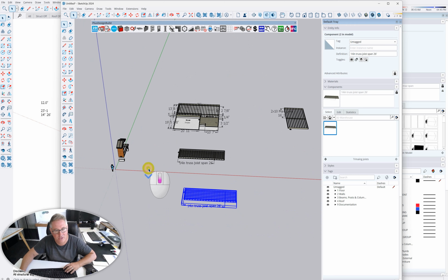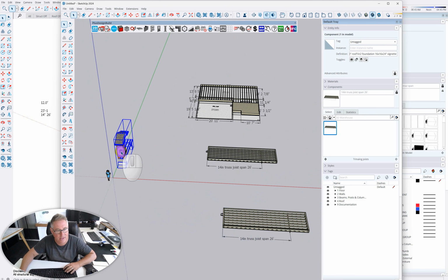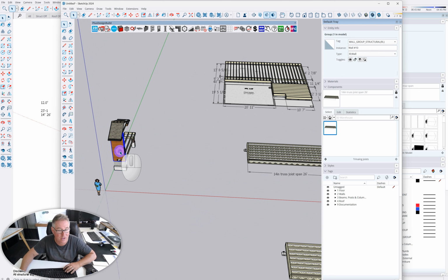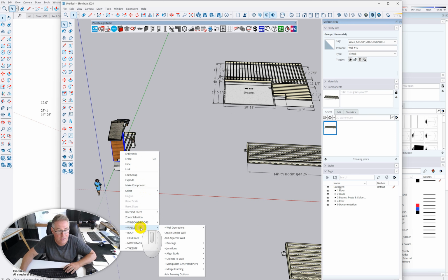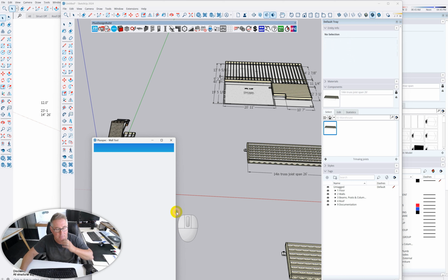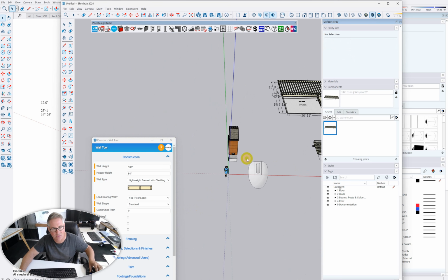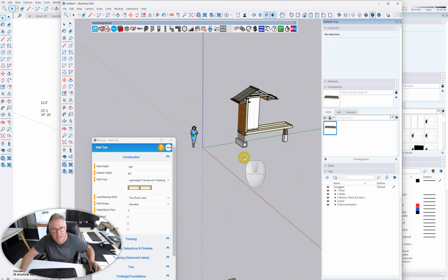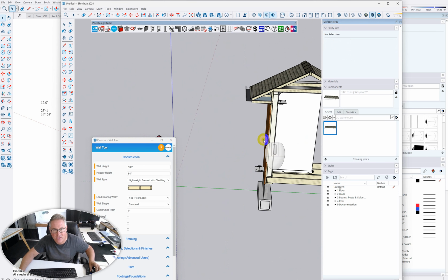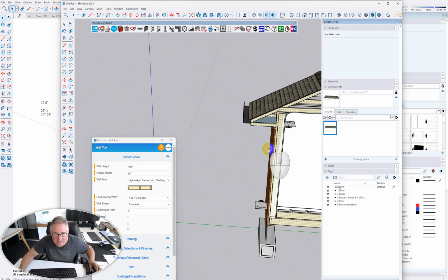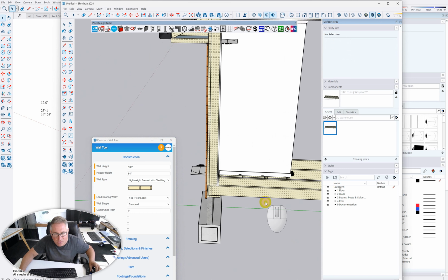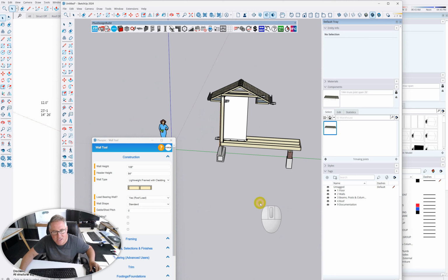So what I'm going to do over here is right click and explode this other vignette because I've already got it saved. I can right click Walls and create similar wall, because the wall already has a set down for my eaves and everything in. I'll see if I can quickly explain that. The cladding is already set down here, and it's set down for an 8-inch joist here, I believe. Yep, it's an 8-inch joist.